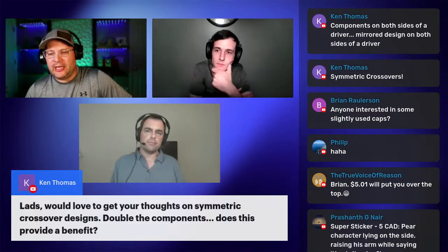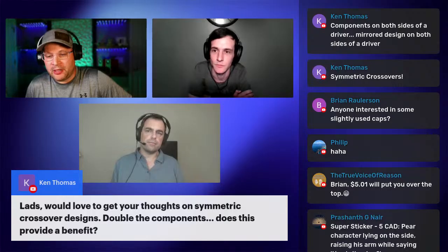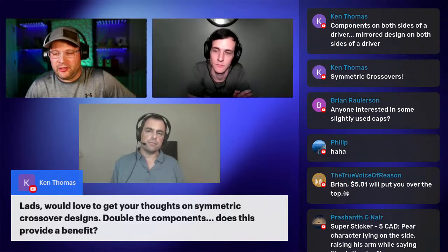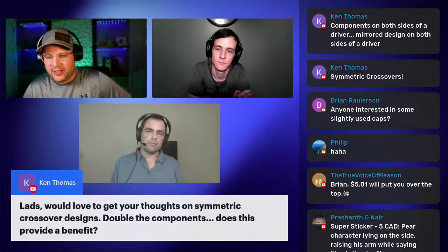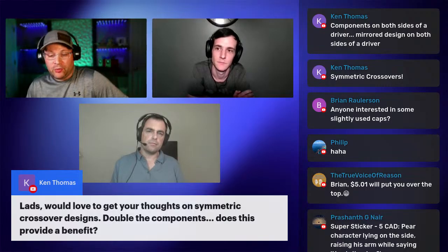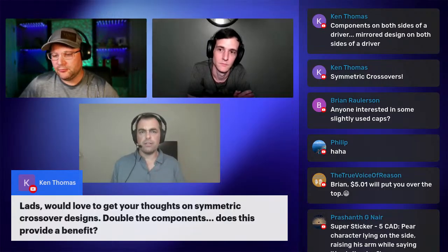I don't love that because, first of all, it's hard to get the phasing correct with that as well. You have to be a lot more intentional when you're doing that. Even driver placement might be an issue to get the phasing and everything correct. I don't think it's worth it. I have put a resistor on the other side of the tweeter, so it's in series, but on the other side just for room on the board or something like that, but not because it offers any performance advantage realistically.